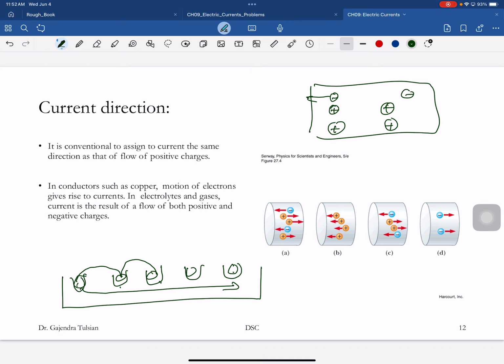So that's what's happening in semiconductors. Here's the band structure. This is the valence shell. The conduction band doesn't have any electrons. Here are a few empty levels, so the electrons fill that, and the empty spots travel to the right. Those are the holes. They're acting like positive charges.